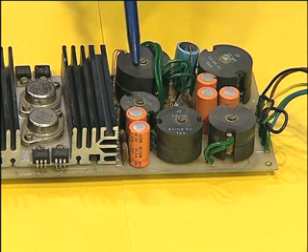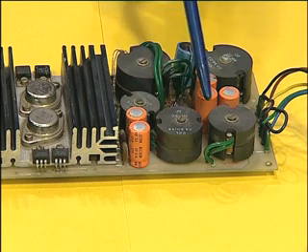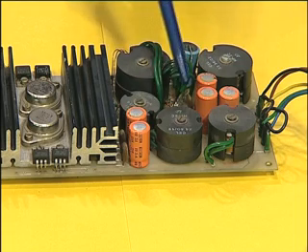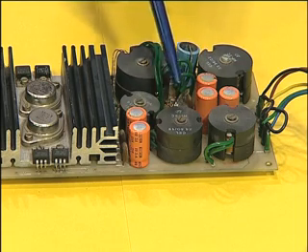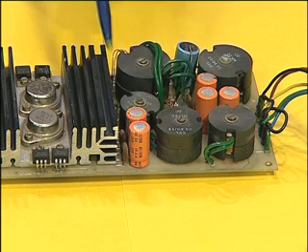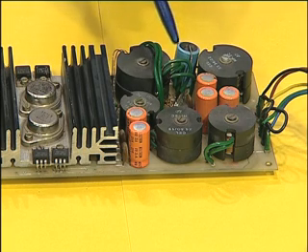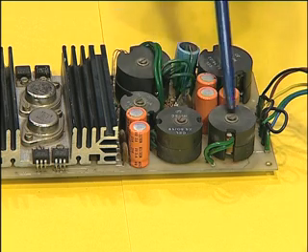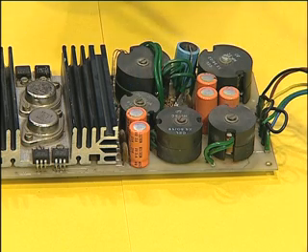They can be used for applications ranging from 20 kilohertz to 100 kilohertz, and special cores even up to 300 kilohertz and further on. If you want to use for low frequency applications like 50 hertz, one has to use not this ferrite material, but the silicon steel material.